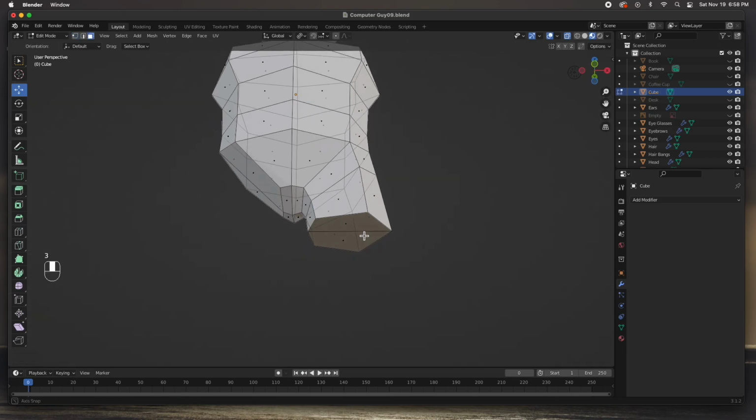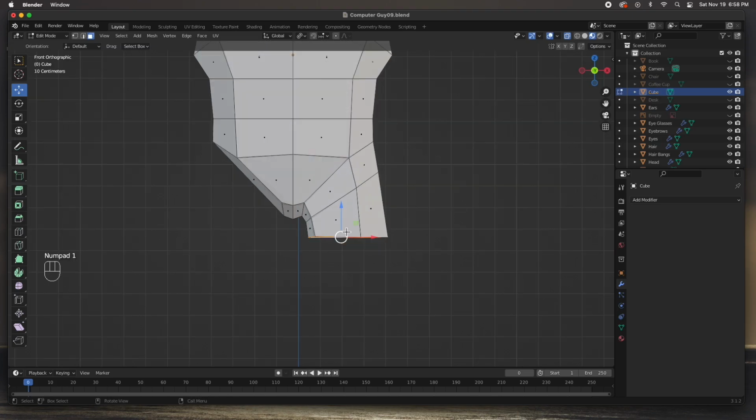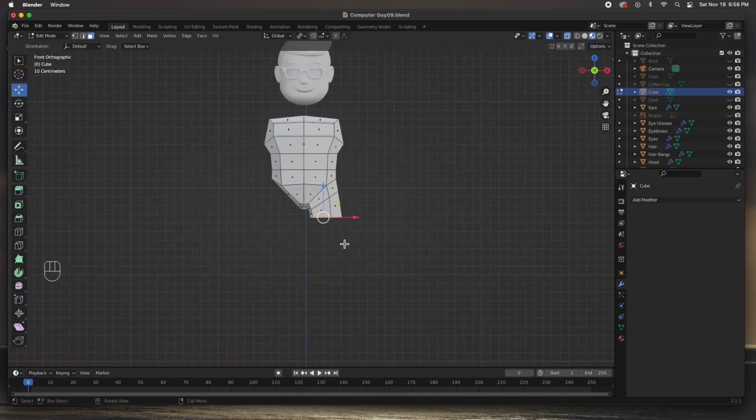3. Select this one and this one. Cool. Let's go ahead and extrude this one. I'm going to hit E and let's extrude it. If this happens to you, it's locked to the Z. Hit Z again and then it will let go. So I am going to extrude it all the way down to where I think the length of the leg should be. And I think the leg should be about that long. And so I am going to scale it to about right there.